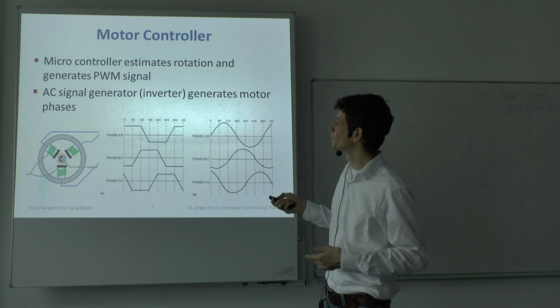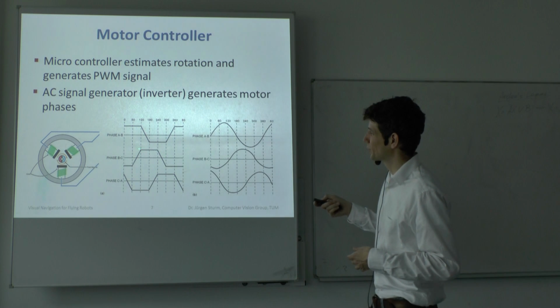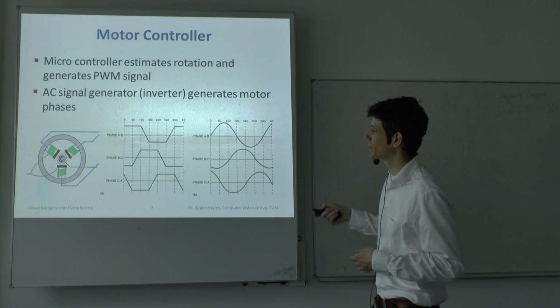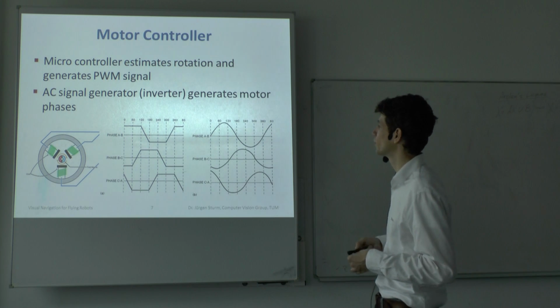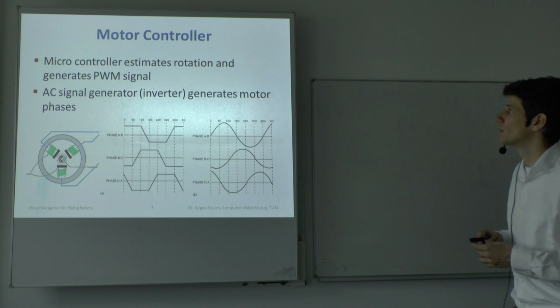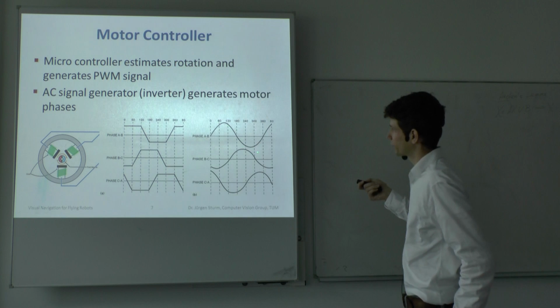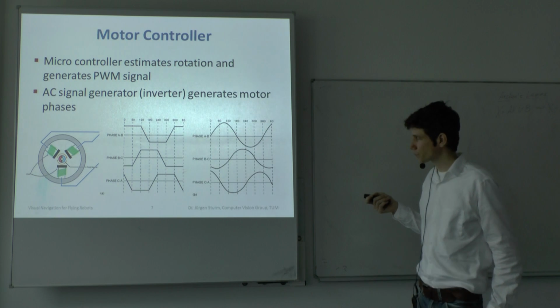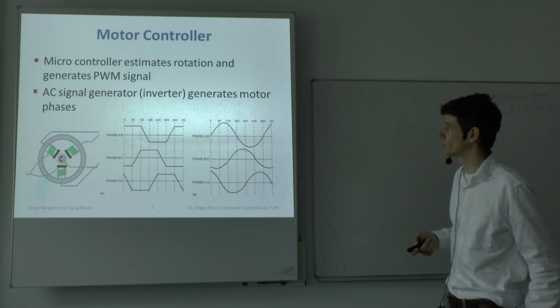This is easier to build, but not super efficient, of course. So the motor is saturated, or the electromagnets are saturated, and this is not optimally efficient. So better microcontrollers produce more of a sine shape signal. And then it looks like this, and that increases the efficiency.